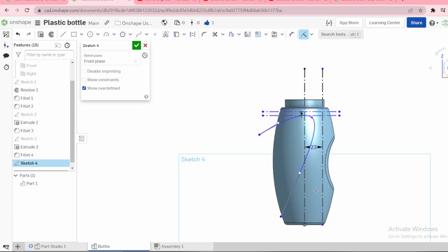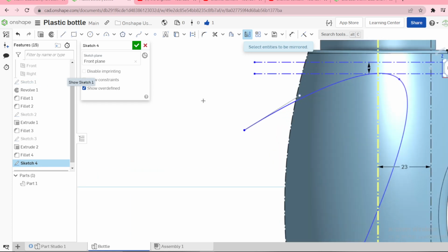On that, I'm going to use a little bit longer method because I want to activate this. I want to show the main sketch. I want now this one to be active. I want to use a U for this. Yeah, that's fine for construction. Then I want to mirror this. I want to use this one as my mirror line and select this like that. Then I can hide. I'm using my main sketch as my master sketch.